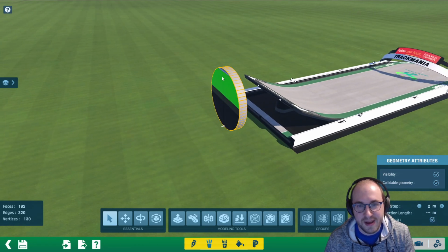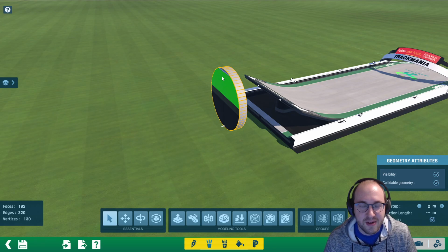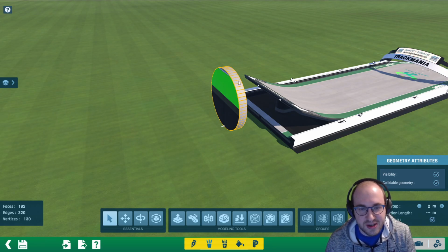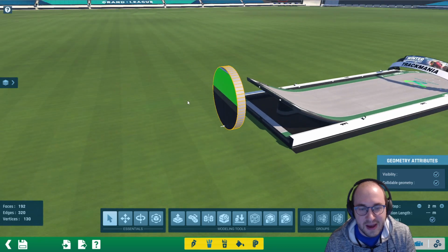Sometimes the faces seem to have a front side and a back side and can only extrude in one direction. So if you're running into something weird like that, try extruding in the opposite direction. So the next thing we need to do then is turn this slice of a pipe into a full pipe, and we're going to do that using the deformation tool.